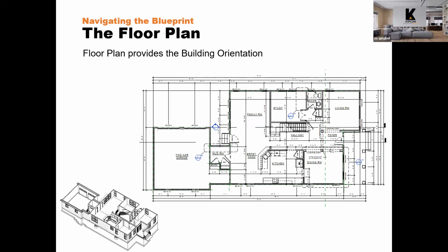Sometimes if there's a multi-level building, you'll see multiple plan sheets starting from either the roof down or the foundation up, starting with a foundation plan. And sometimes, if there's a parking garage, there might be a parking garage layout plan. If the parking is either at ground level or below ground level, you'll see those first. And then there's a first floor layout and one for each successive story up to the roof.